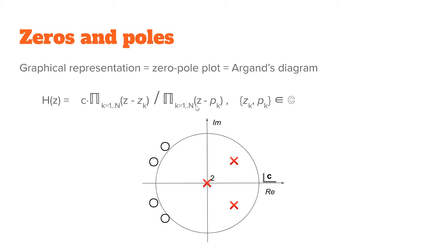If the poles are here, then it's stable. And if I draw a circle like that, j omega c, minus j omega c, so the radius is omega c, and mark a couple of poles like this, recognize the filter. It's a low pass type Butterworth filter.